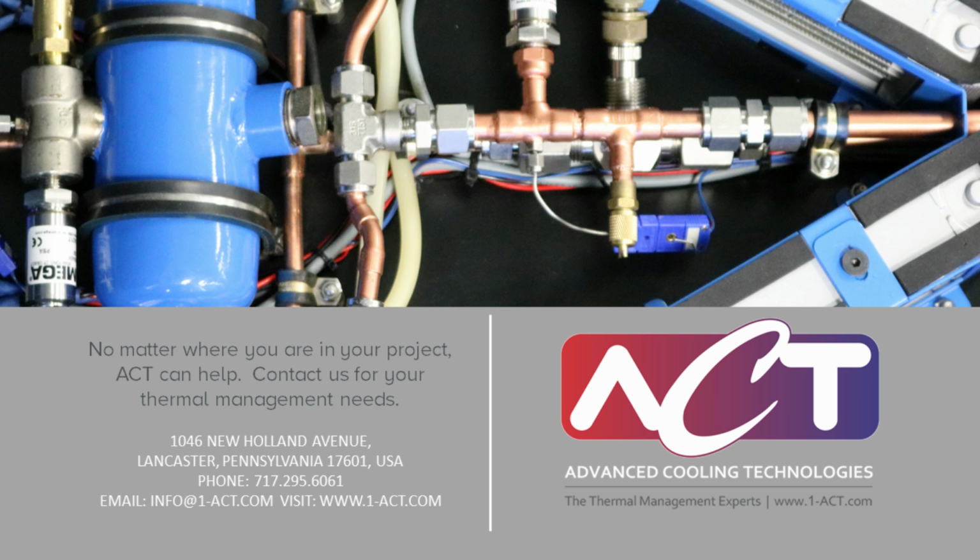Thanks, Ryan. Someone wants to know, what other temperature ranges can heat pipes operate in? Good question, and this will be a short one. Really, you can go all the way from the cryogenic temperature ranges to the very hot, 1,000+ degrees Celsius temperature range. So the common working fluids that I've seen are the ammonia-based systems, water. Sometimes you'll dabble in some methanol, which kind of envelopes water and ammonia, or is enveloped by those.